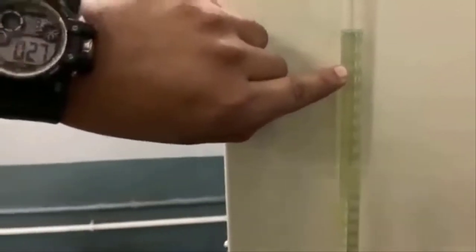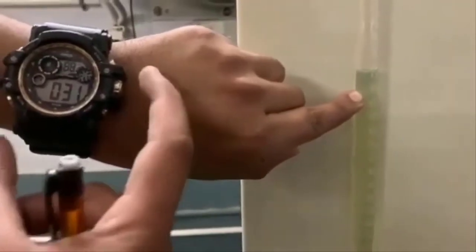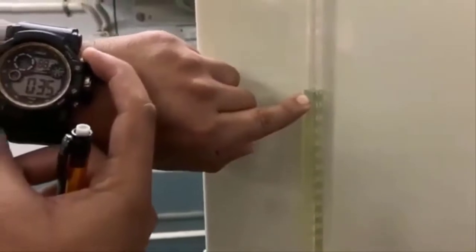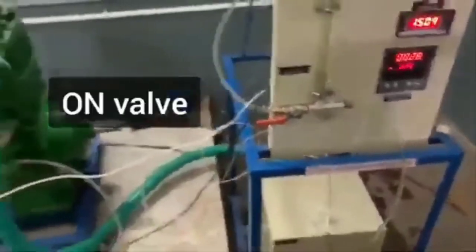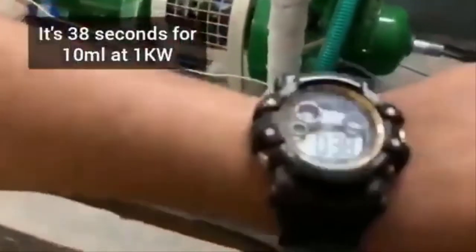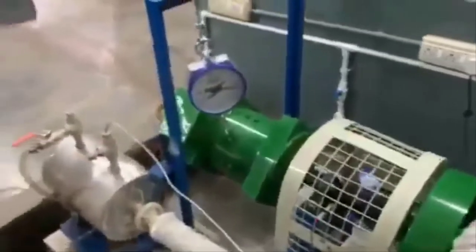Here you can see it is the 10 ml end. This is the final level, up to which we take the stopwatch. Once this level is achieved, we just stop it. You can see the stopwatch ended at 38. So in 38 seconds we have measured that 10 ml of fuel is going inside the engine at exactly 1 kilowatt. This is how we can take all the measurements.